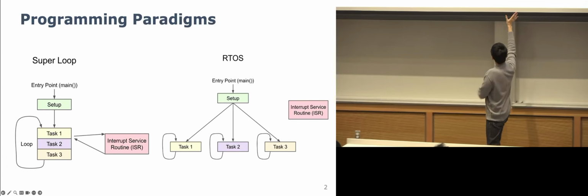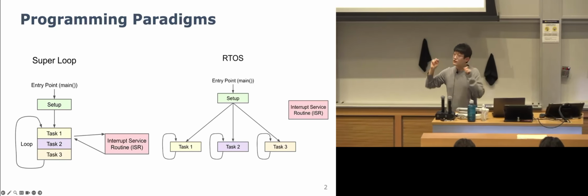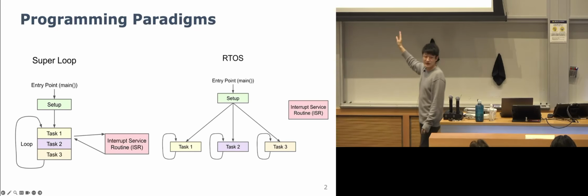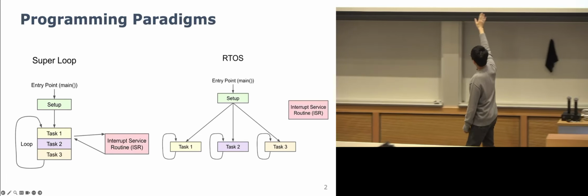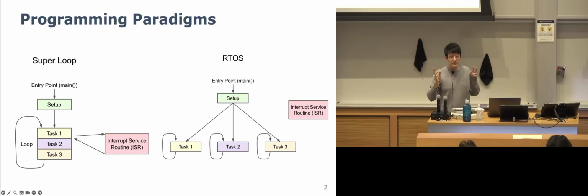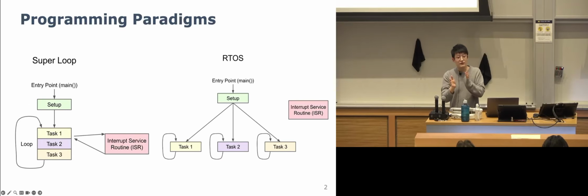For this one, each task has its own allocated stack space, so you will be using a different stack pointer, the PSP, the process stack pointer. Interrupts use the main stack pointer. Each task has a task control block, TCB, and memory allocated for it in SRAM for the stacking.